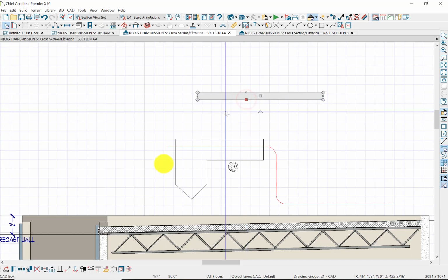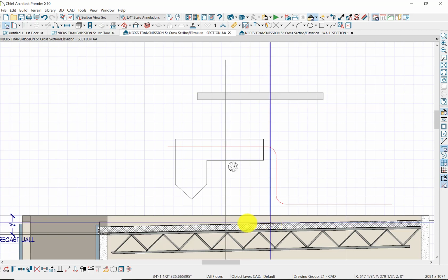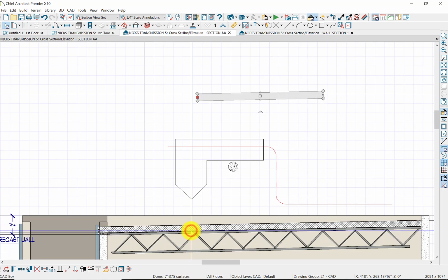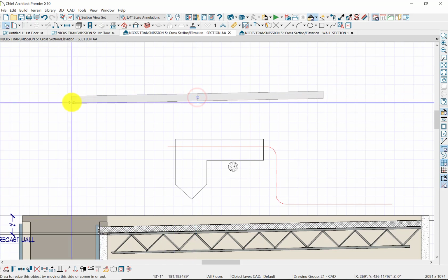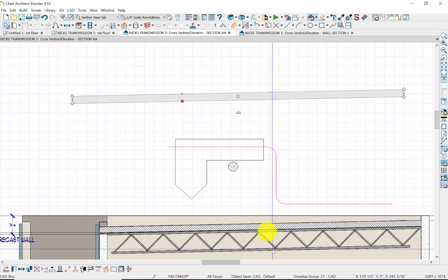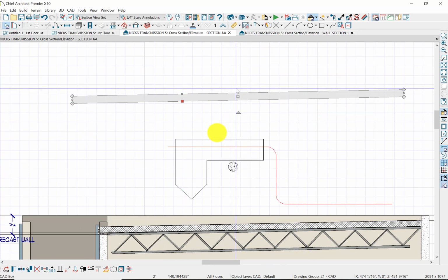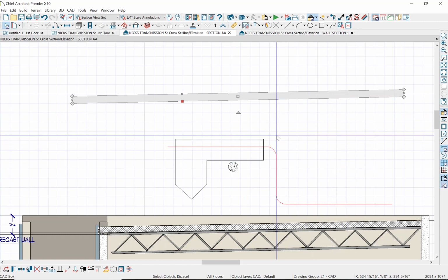So we grab that. We use a perpendicular tool. Point to something that's perpendicular to that. Hello. Give me something perpendicular, will you? That lines up there. Let's say that one. And now it's at the 1/4 inch. And now we can slide it. Now it's exactly a 1/4 inch, because this is exactly a 1/4 inch. And we can use our fill commands, whatever we need to do to render it up. So the box is a very cool 2D tool.